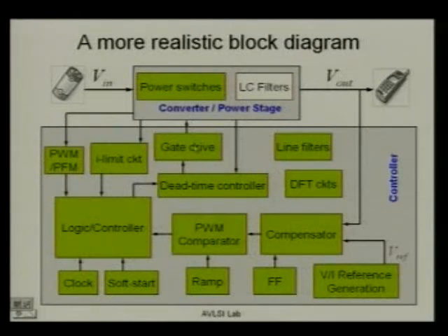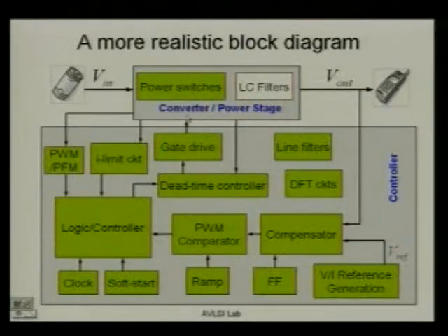Gate drive. So long I have mentioned that the MOSFET is switched using a switching signal, but if you just get a switching signal, a square wave out of, say, your comparator, your LM339 or whatever you have, you cannot put it into a MOSFET and your MOSFET won't run, because the MOSFET gate requires a large amount of current to charge it up. The MOSFET gate has huge input capacitance, right? Hence this driver circuit.